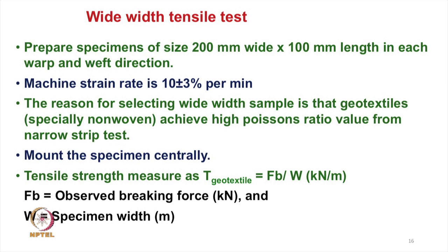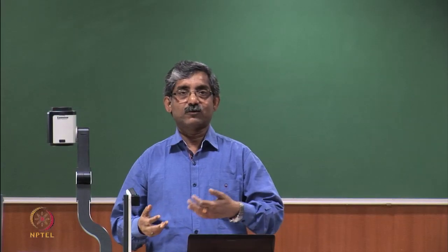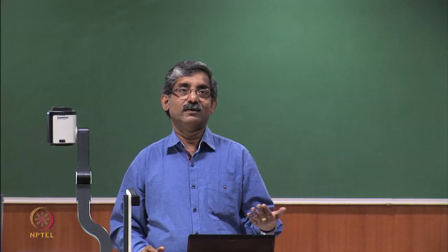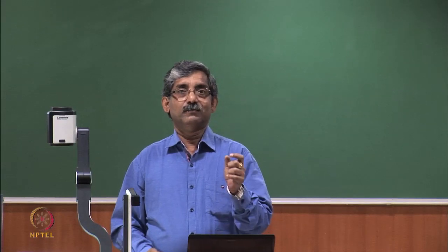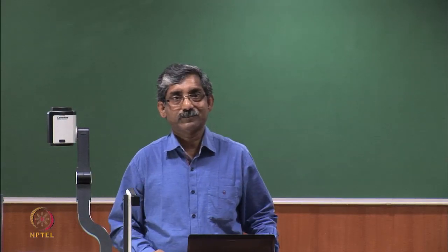We need to do the wide width tensile test because when geotextile is laid under the ground, this wide width tensile strength actually simulates the in situ condition.